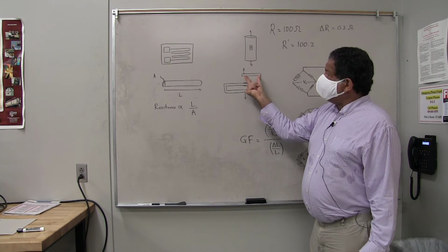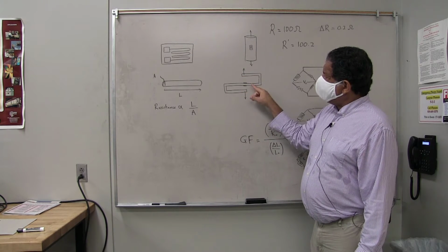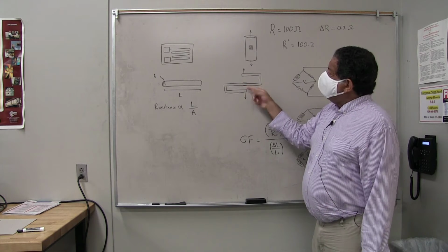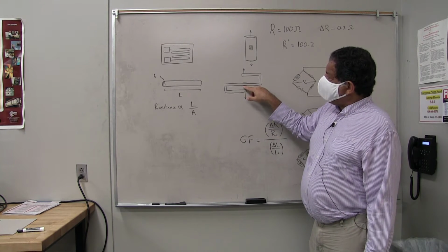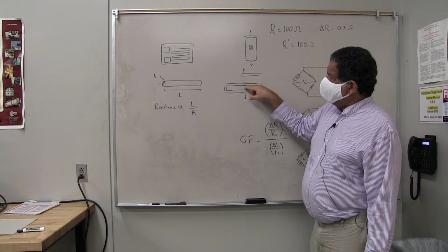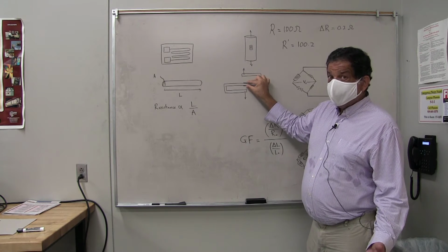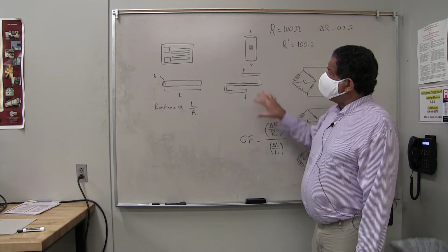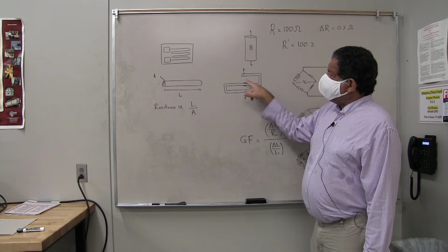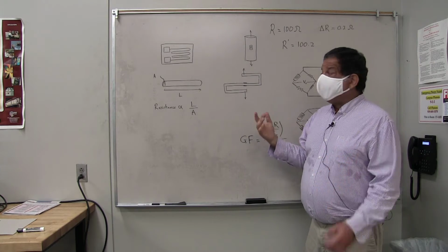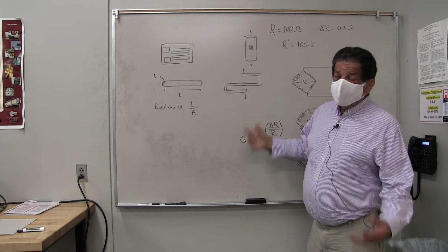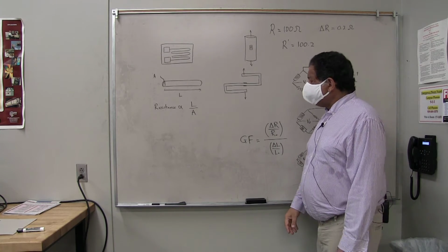So the bending moment in this object over here is going to be bigger by this divided by that ratio. And so you're going to get a much bigger displacement or strain on these 2 strain gauges that you put on the top and the bottom of the beam than you would have gotten on a straight tensile member. So typically in load cells, you'll find arrangements like this designed to create a larger strain signal per load than you would get in a straight member.